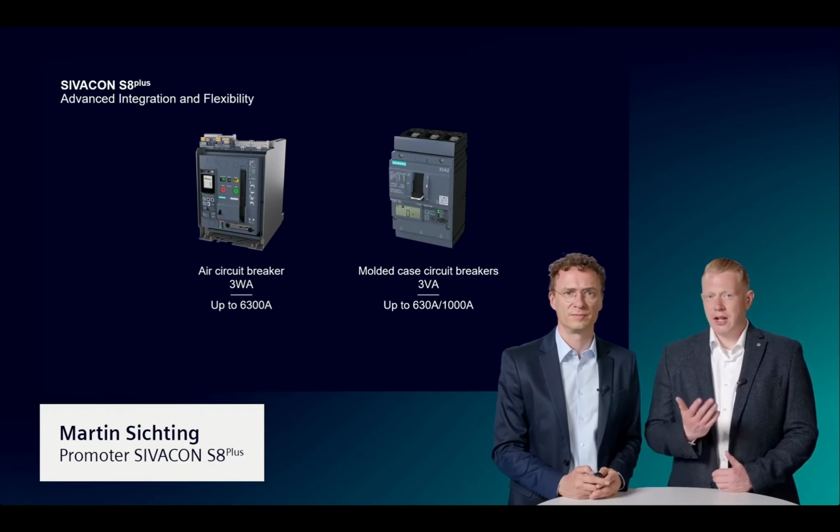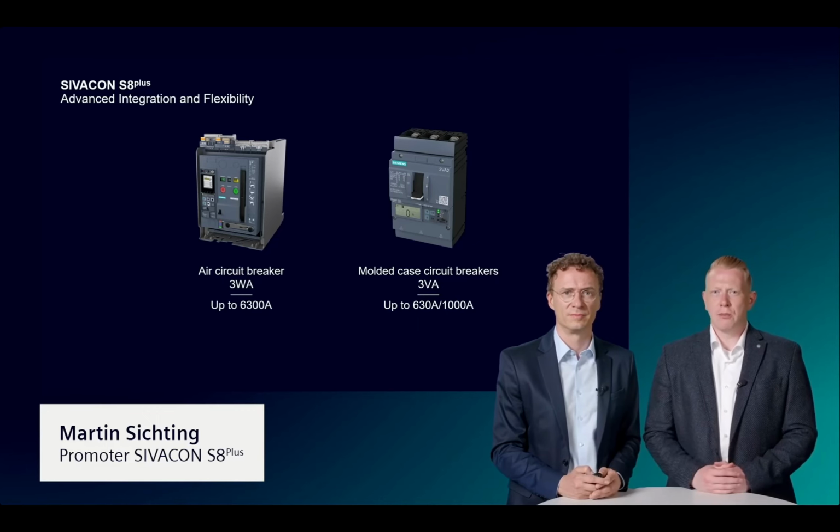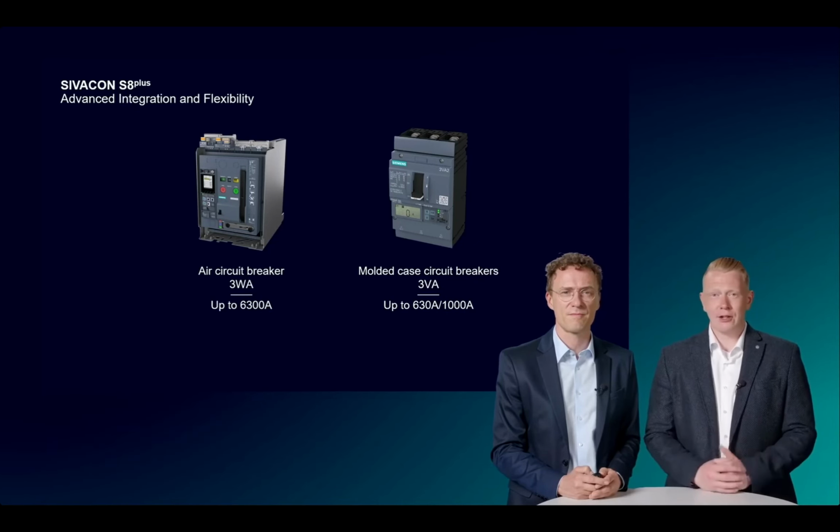In the feeder, particularly for large consumers, the circuit breaker protection design is used. For higher ratings up to 6,300 amps, we use the 3WA air circuit breaker. The way to identify short circuits is the same as in our previous drawing. This is called a breaker and a half deployed in a substation. And the decision is whether we build up a separate circuit breaker section with one or up to 3 breakers.